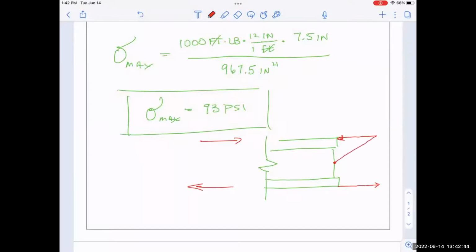So in the end, if you draw this triangular load right here, this is an example of a place where it's causing triangular loading. So the maximum is right up here, and it's being loaded less and less as you move down, and therefore the middle fibers are not getting as short as the top fiber is. The top fiber is getting the shortest, and then they get progressively less until they go to 0. Over here, it's just doing the same thing, but going the other direction. So notice the arrows. This is compression, this is tension. That's what's happening in there.